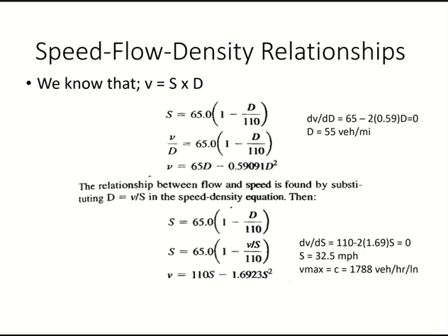Which we call critical speed. It's before capacity, right? At capacity. Okay? This is the speed at capacity. Maximum flow is what? Capacity. Slope becomes 0 when? At capacity. Clear? This whole thing is happening at capacity. Slope becomes 0 at capacity, and this is the d value at capacity because I got it from here. Same thing here. The slope becomes 0 at capacity, and this is the speed I got at capacity because I got it from here.